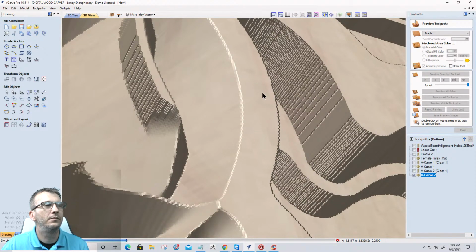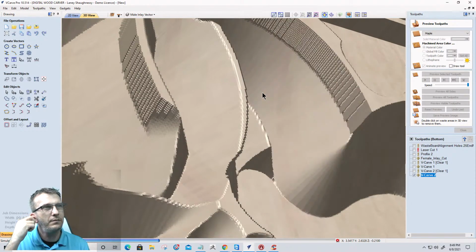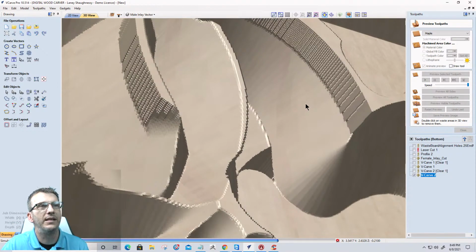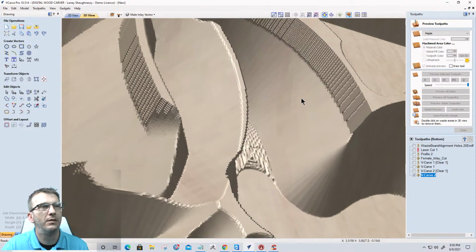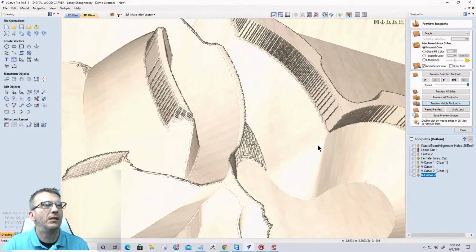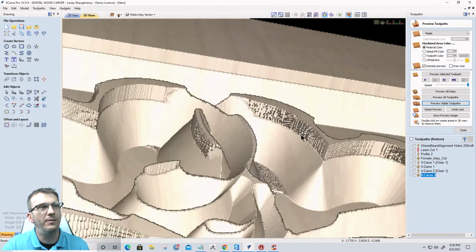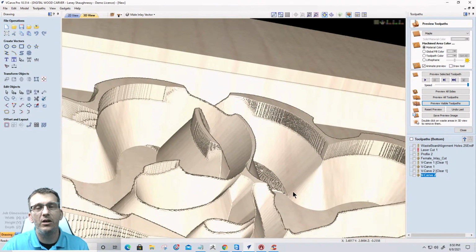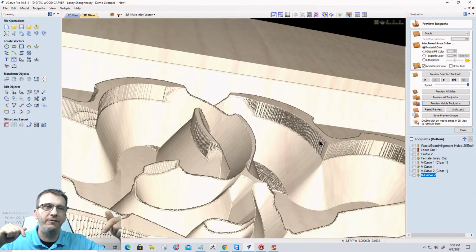All right. Okay, now we can see. Let me let it finish up and then let me zoom out. Okay. So you see this straight meat here at the top of the cut before the V-carve starts. That is the shank of my bit, that vertical cutter on my 1/4 inch end mill. That's showing I'm exceeding my cutter's depth, and my shank is colliding with that edge. It creates this straight edge, and that is not going to fit into my female inlay.